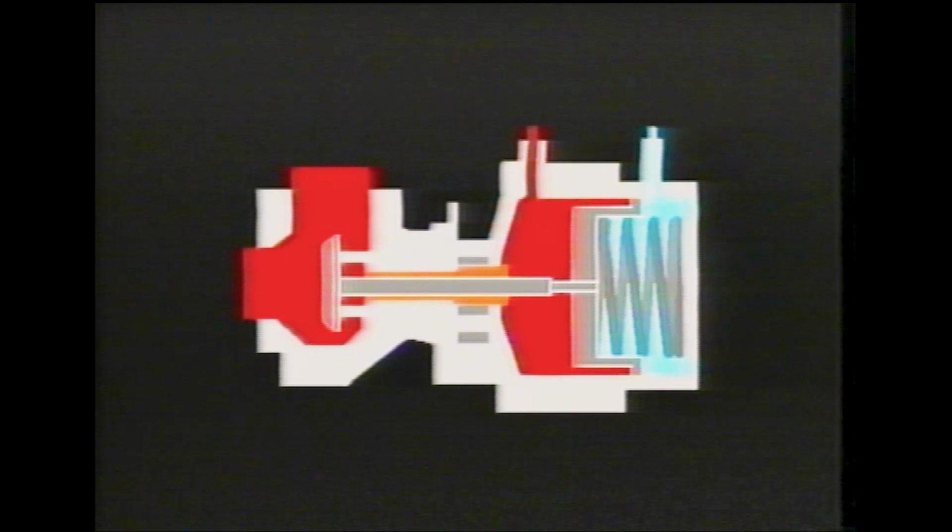To ensure that the valve opens still further at an appropriate speed to prevent the engine from pinking, the diaphragm movement is assisted by depression, which is channeled via a flexible hose from in front of the impeller, where the depression is created by the increased speed of the intake air. The combination of exhaust pressure and depression ensures that the boost pressure is maintained at the optimum figure of approximately